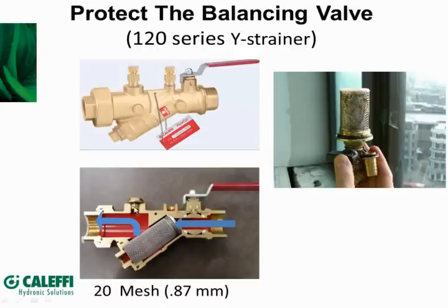Well, many times people will periodically measure the pressure drop across the Y strainer cartridge. We have a couple of taps here. I don't know why that tap's missing here. But at a certain value, a pressure drop would indicate that there's a really big plug of debris in here. And so in that case, the installer would pull off this cap, pull the strainer out, clean it out, and put it back in service.